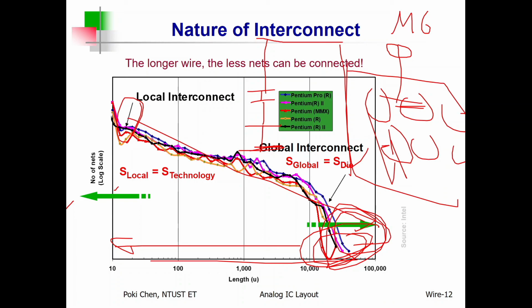So in practice, we don't use such top metal to connect many nodes. No, very few nodes, but for a long distance, got it? For very short distance, usually we apply metal 1. If you have a look at this again, the device contacts metal 1, then contacts the other device, and the other device, and so on. So for such metal 1 connection, it is much easier, right? Usually it is for local interconnect, and it can help you connect a lot of nodes locally in a short distance. Okay, that is the truth, not only for Intel, but for almost all the companies on Earth.